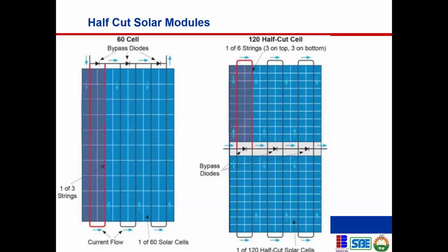Thank you, sir. Training, there are different configurations. So it all depends on how you connected them. If you connect the two of them in such a way that you have essentially reduced the output from the higher efficiency panel to that of the lower efficiency panel, that's what you've done if you're connecting both of them in series.